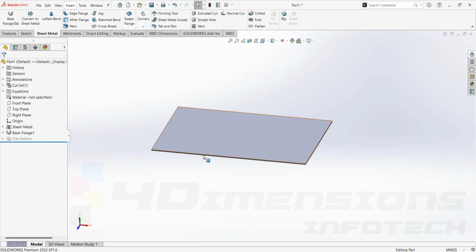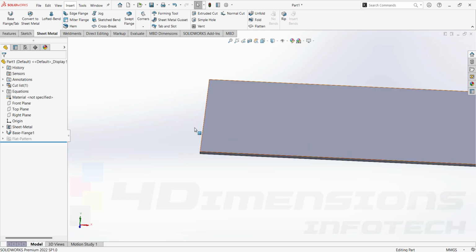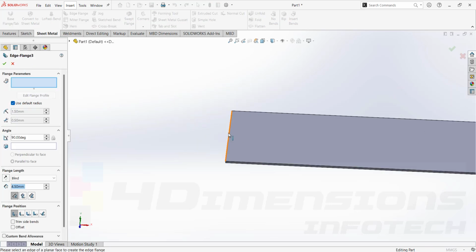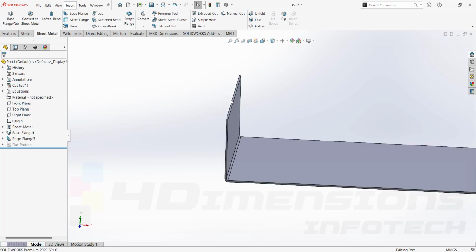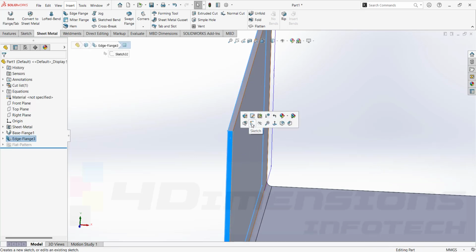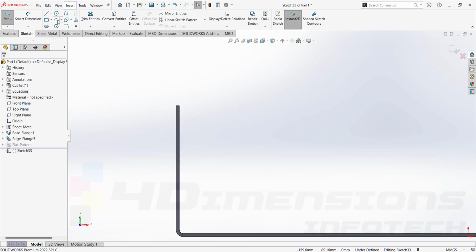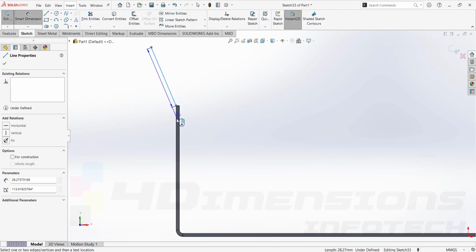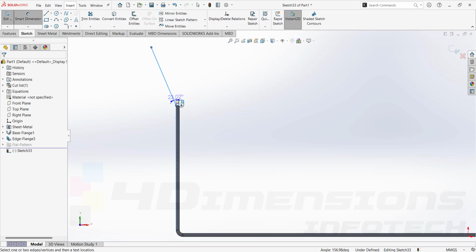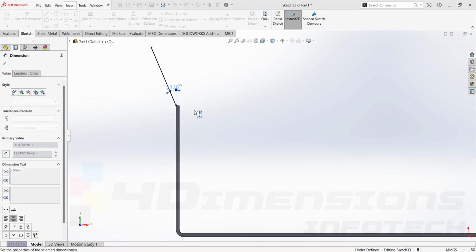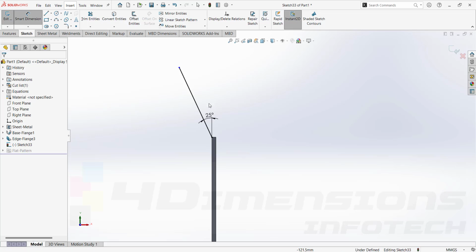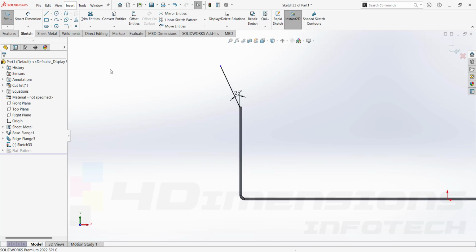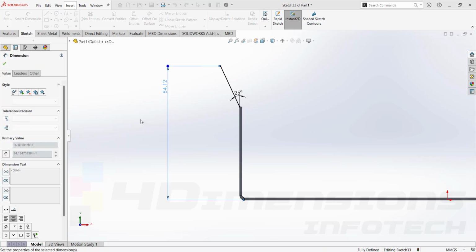And now I'll start with swept flange. For that I have to make profile on the cross section. Suppose I am going to make one edge flange. Say it OK. And now I select this flange face and directly go for one line here from the outer point. If I want to give an angle, I'll provide the angle also there. I have taken 25 degrees angle and flange length as required. Instead of giving the incline length, we can prefer the length from the bottom side to the top end of the part. I'll say 80 mm here.